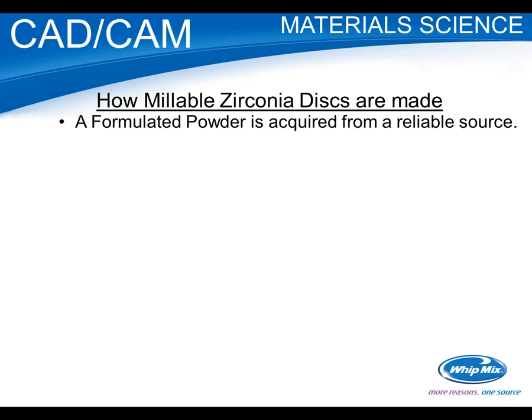Some aren't. I know there's a source out of China, and I know a major player out of Europe uses that, so I presume it's a good source. I'm not discrediting it. I think most of the suppliers of zirconia have found the problems early on. There's an issue with radioactivity because one of the isotopes that are found with zirconia in nature, I think it was thorium, has a low level of radioactivity. And so if you look at specs on zirconia, they still include a requirement for radioactivity, though I don't think that's really an issue anymore.